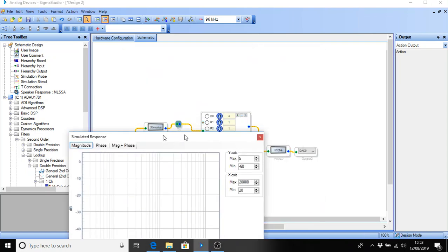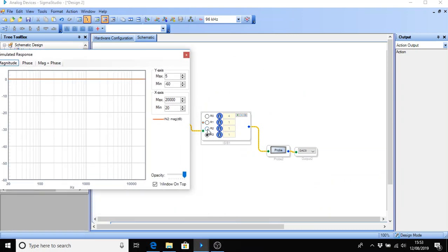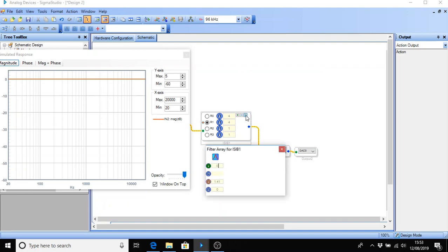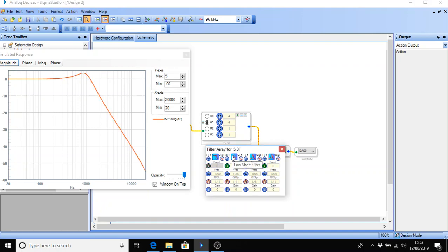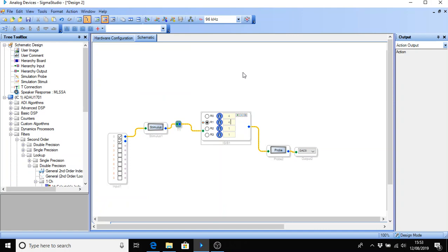and the stimulus, you can see that this is the fourth filter here, third filter, the second. These come pre-programmed, and this is the one that we've built. If we were to build the second filter, let's make that a 4-stage filter as well. This little square in the corner gives us the picture of the filter. We can turn this into a low-pass filter as well. You can see as I add the components, it has an effect on the shape of the curve. I'm not going to worry about actually building that filter right now, just to prove that it can be done.